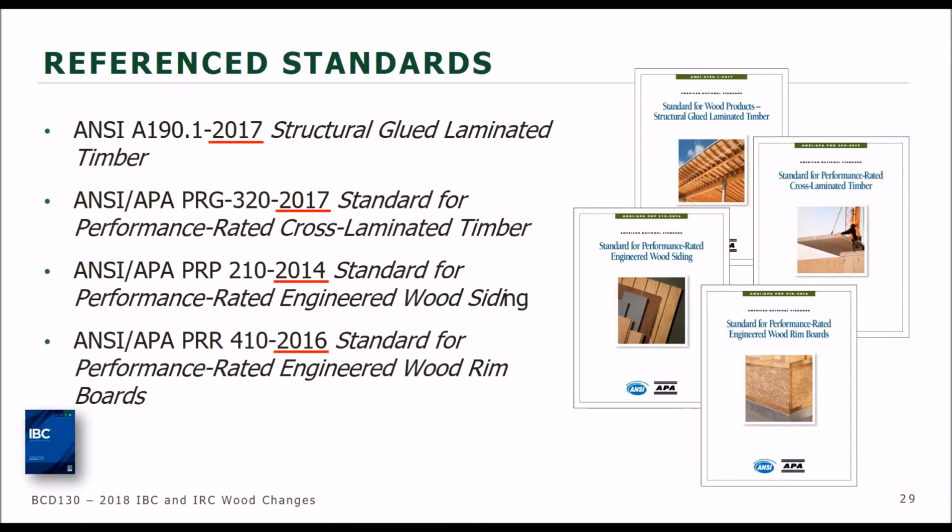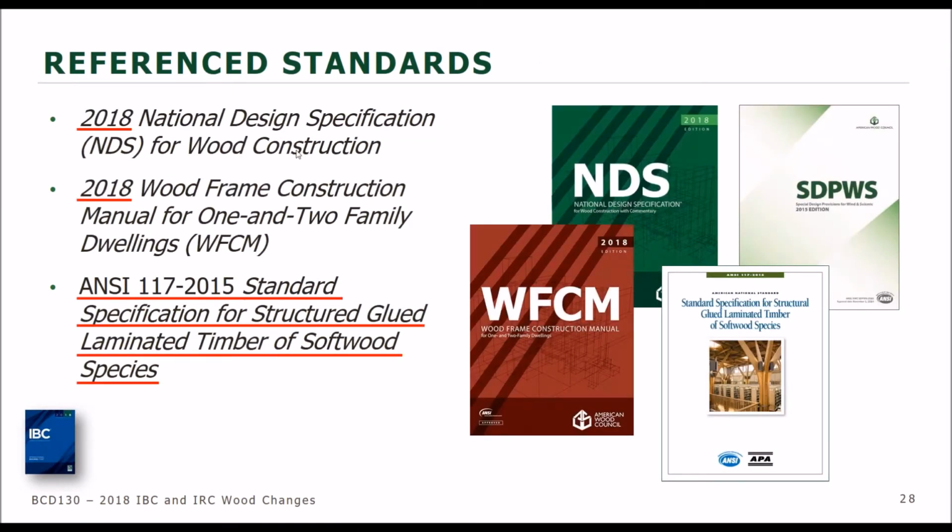Oh, the one thing I should note is back on this slide related to the design of wood structures, the NDS and the wood frame construction manual have been updated, but the wind and seismic provisions of the 2015 edition still remain. That has not been updated. That will probably be updated in the next code cycle. So no changes there related to the wind and seismic provisions.